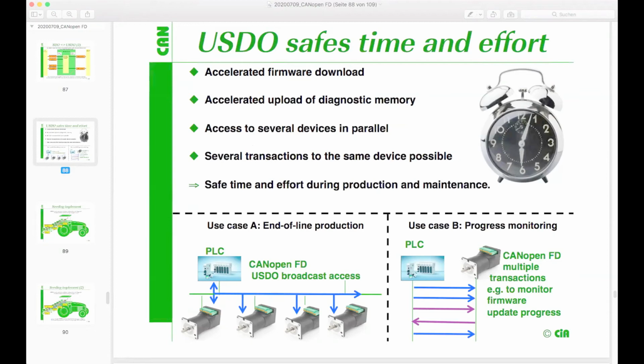Yeah, it's a little bit different on the CANopen FD side compared to classical CANopen, but if I understood your question correctly, yes, I can have parallel access from several CANopen devices to the very same CANopen FD device that then acts as a server. This I explained, as it's rather simple to modify now this first data field.